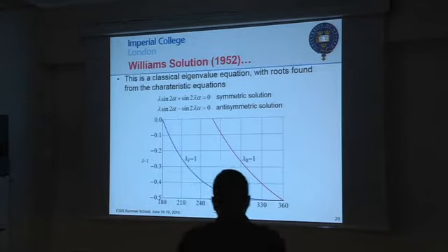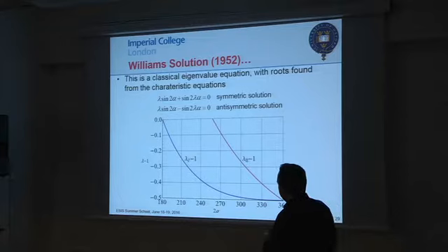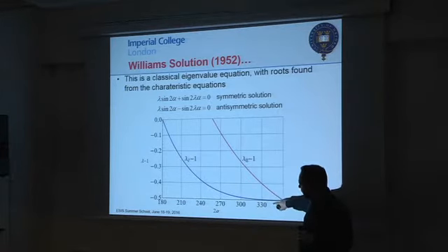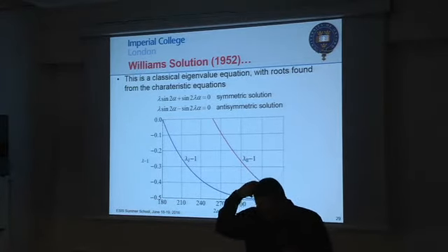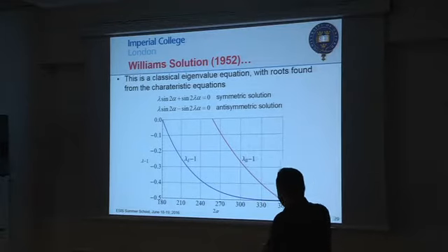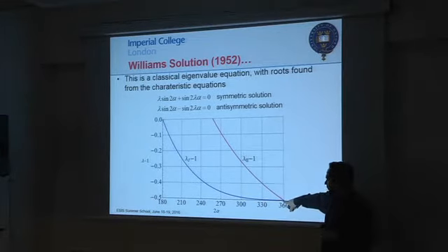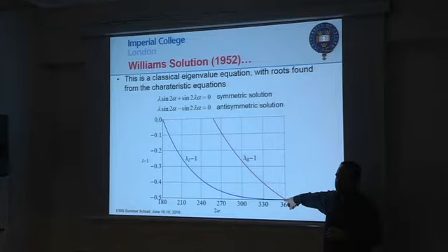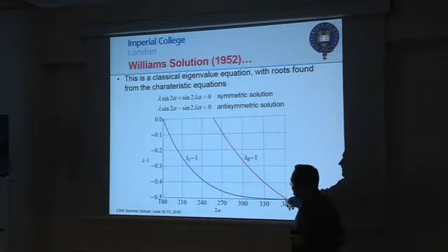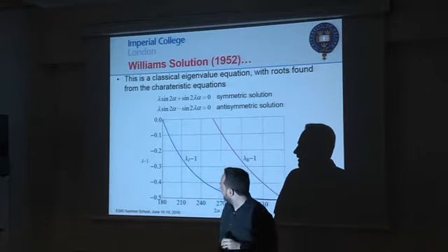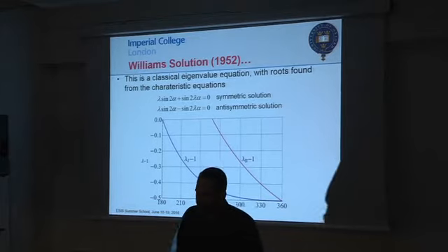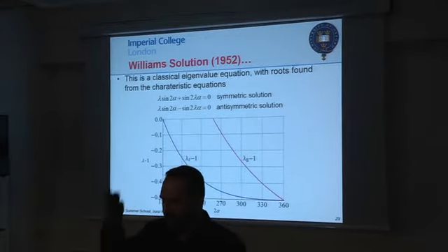And here is what lambda 1 does. Lambda 1, and I'm plotting lambda 1 minus 1 because it's convenient, goes from minus 0.5 to 0. The minus 0.5 corresponds to the well-known solution for a crack, where you have a square root of r as being your solution, and zero corresponds to not having any singularity for a flat sample.